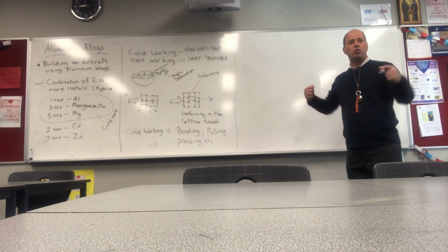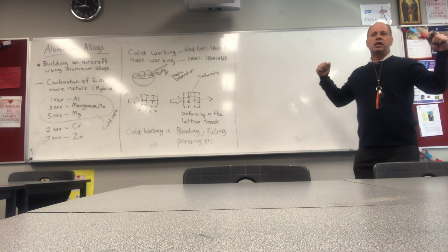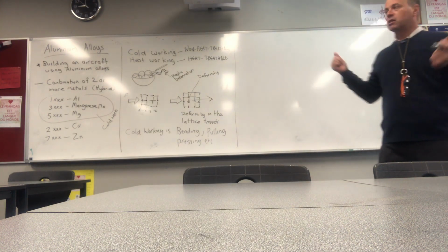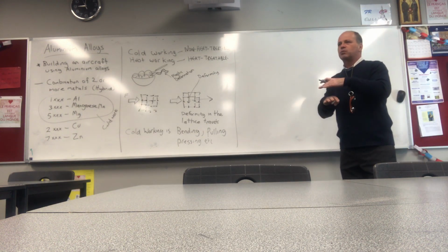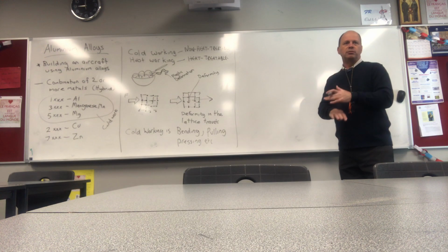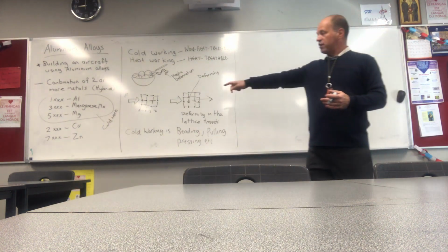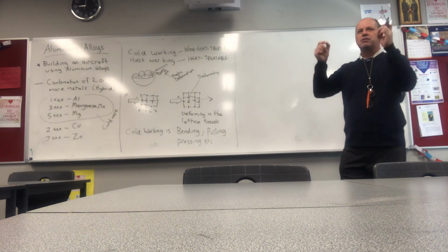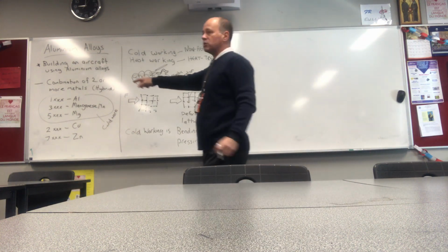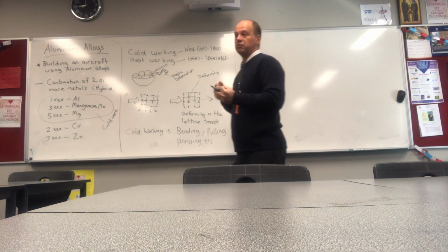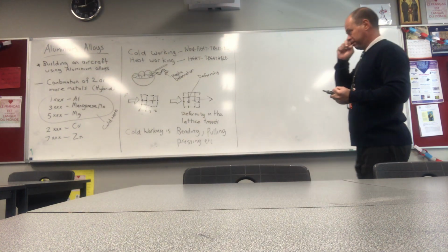Obviously, if you keep cold working, it gets harder and harder, and eventually it gets brittle and it breaks. Okay, so there's benefits and disadvantages, and it's a balancing act between being hard but not being brittle. And you'll find that all these alloys are tweaked with different percentages of different trace metals to try and get the perfect material for the position that it's being used in.